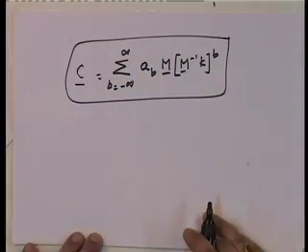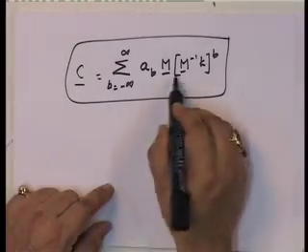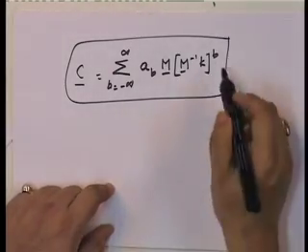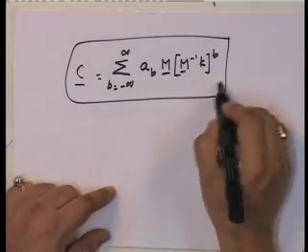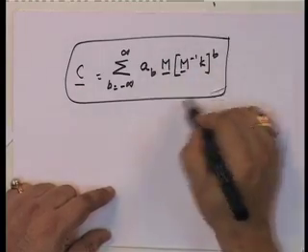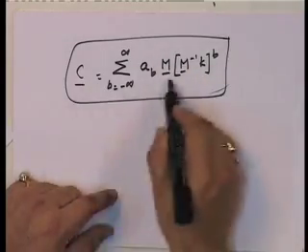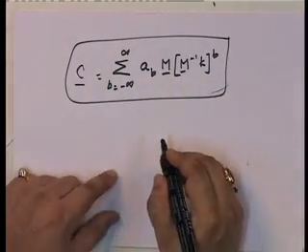If C is of this form, it is also proportional, because we have shown that this is proportional. In other words, we have shown the orthogonality condition. So if it is a linear combination of all of these, automatically C is also orthogonal. I mean, the mode shape vectors are orthogonal with respect to the C matrix.